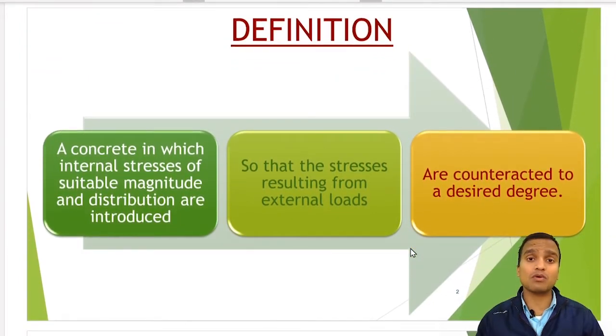You must be remembering in the definition of prestressed concrete, we discussed that prestressed concrete is also a concrete just like RCC. But unlike RCC, in PSC we introduce a certain amount of internal stresses before the external load is exactly applied. These internal stresses are of suitable magnitude and distribution throughout the length of the member, and are meant to counteract the stresses resulting from the external loads to a desired degree. We introduce these internal stresses in PSC by two methods.